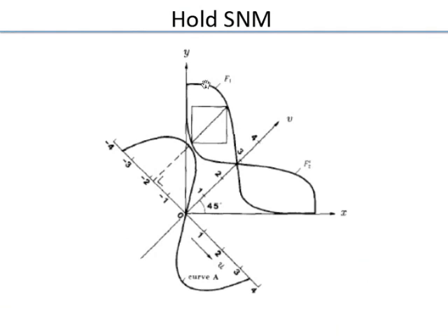So here, if you see, the distinguishing feature is that, just ignore this stuff out here, okay? Because I cut and pasted it; just for simulation we do this. Just focus on this XY, and you have the same DC transfer curve, except now, because I'm not reading the cell, that access device is not degrading the value, it's just holding. So here when input goes all the way to VDD, output does go all the way to ground.